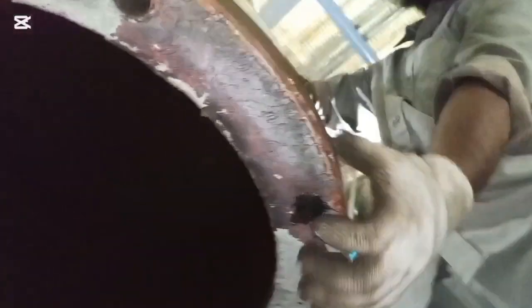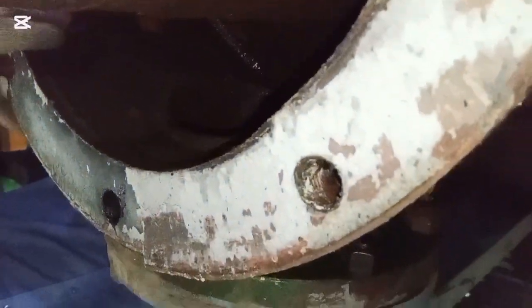There are two types of ejectors: single stage ejector and multi-stage ejector. The simplest is the single stage ejector, featuring a single motive fluid nozzle, diffuser and mixing chamber. On the other hand, multi-stage ejectors combine multiple single stage units in series to achieve higher vacuum levels.